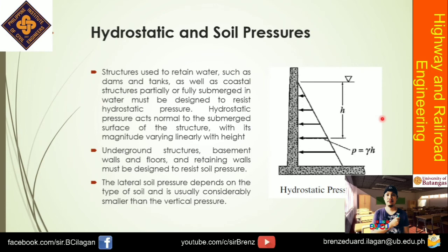Okay, structure used to retain water such as dams and tanks as well as coastal structures particularly are fully submerged in water must be designed to resist hydrostatic pressure. Hydrostatic pressure acts normal to the submerged surface of the structure, with its magnitude varying linearly with height. Underground structure, basement, walls, and floors, and retaining walls must be designed to resist soil pressure.